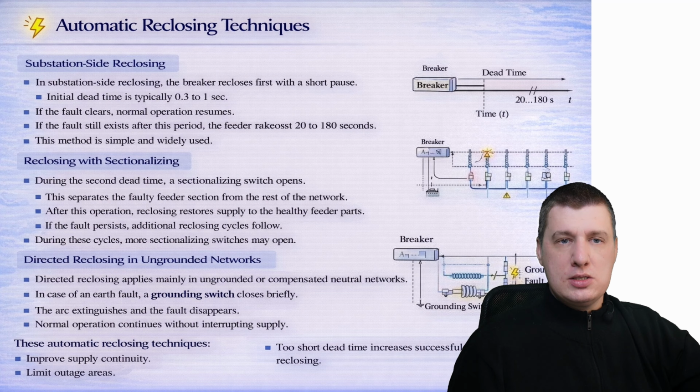If the fault remains, a longer time follows, typically 20 to 180 seconds. If the fault still exists after this period, the feeder disconnects permanently. This method is simple and widely used. Reclosing with sectionalizing improves fault isolation.